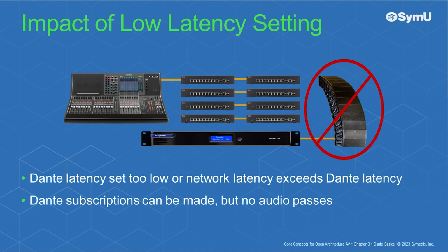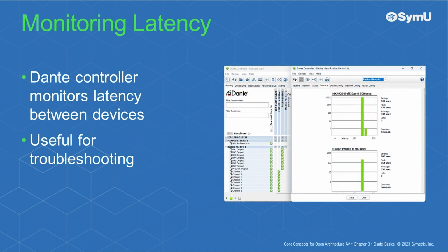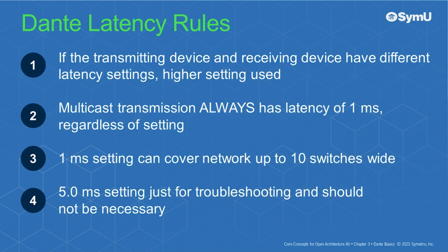Dante subscriptions can be made, but no audio passes. Dante Controller can be used to monitor the latency between devices on a Dante network, which is very useful when troubleshooting. Here are some Dante latency rules to consider.